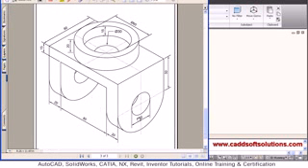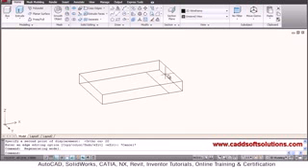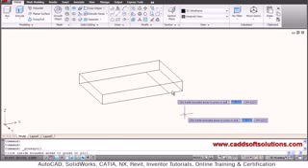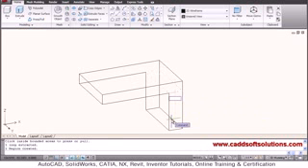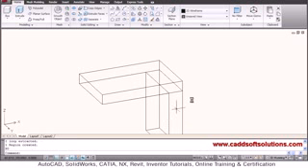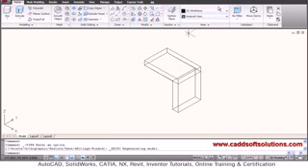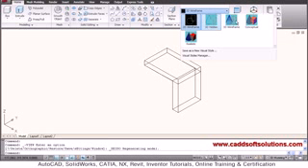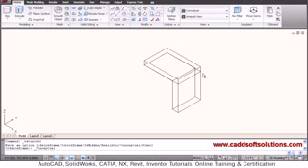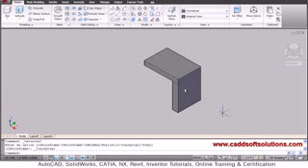So we will just press pull it. The height will be 50 plus 80 is the diameter, 80 is the diameter, that means 40, so 90. So we will press pull it by 90. We will just say press pull, select this portion and give a height of 90. So this portion has been press pulled. So we will move back to southeast isometric. We will just see how it looks in conceptual visual style. So in this way this object is created.